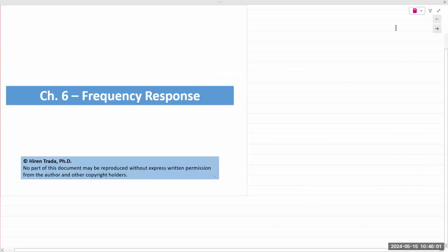One more point about the example we just did, example 5. The approach we chose was combining into one single impedance, ZEQ, because it's in series. If it's in parallel, your approach would be different. You would still combine in ZEQ, but slightly different. If it's a series parallel circuit, or if you have more than one source in there, your approach would be different. Okay. So again, draw out the equivalent impedance diagram, analyze it as you were analyzing a DC circuit, and then do the math afterwards.